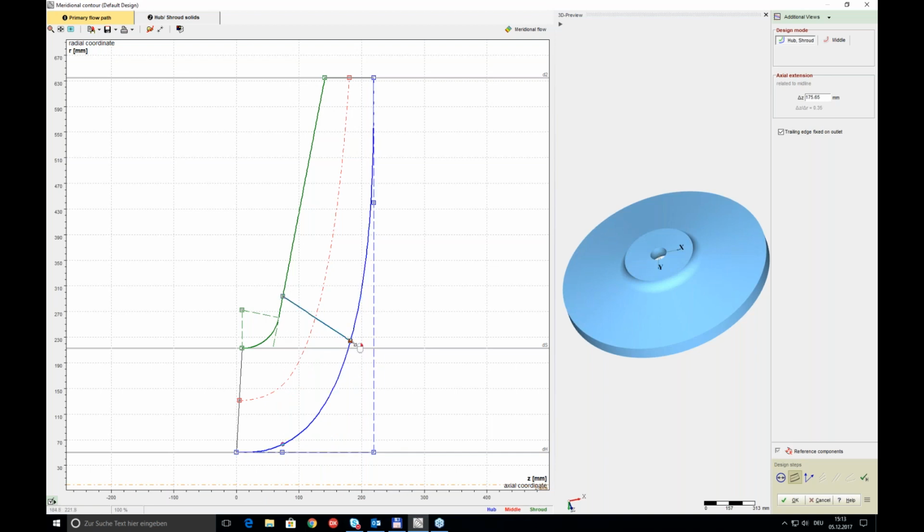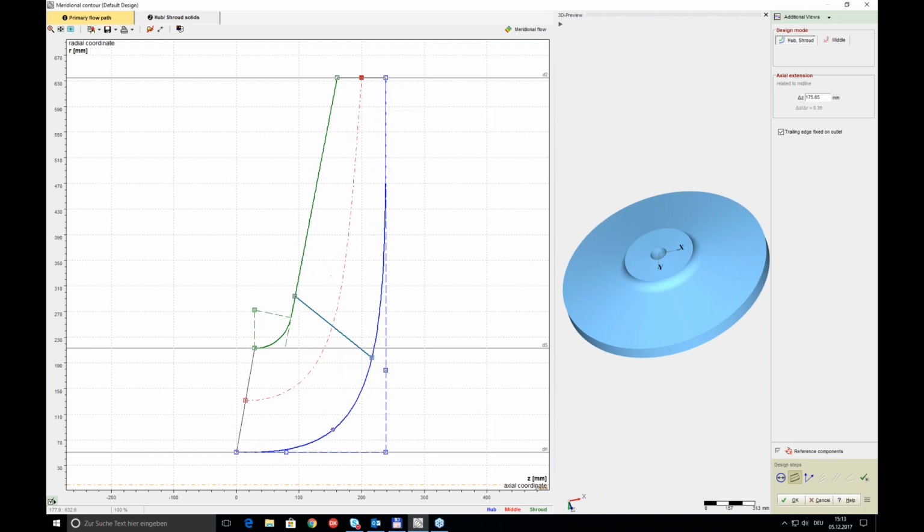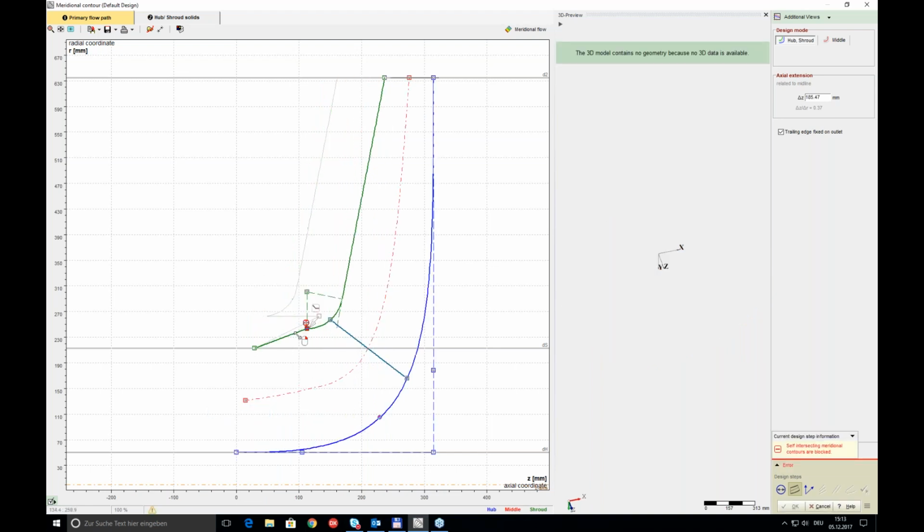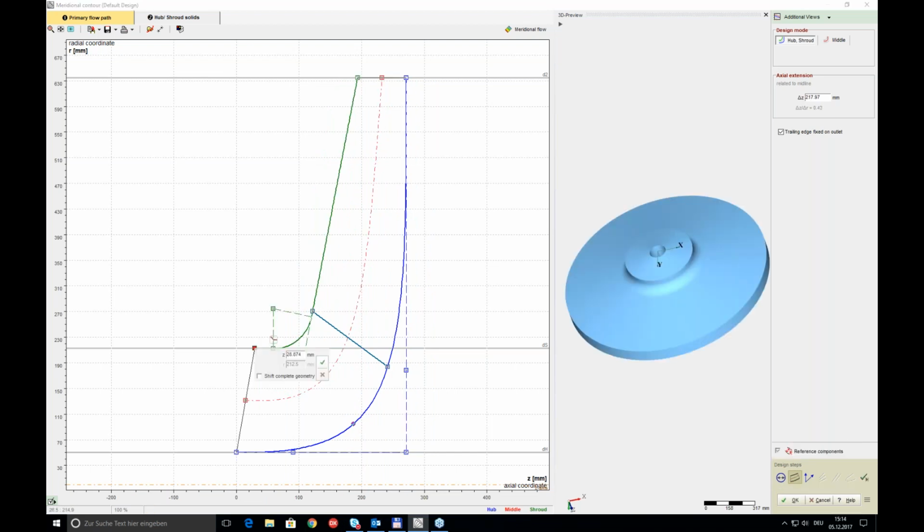And very often for centrifugal fans, impeller as well as the volute are made of sheets of metal, and that's why I leave the shroud contour to a linear part and a circular arc part. So the only one I'm going to change here is the actual extent, which can be 200, for instance. And I want to have here another linear piece at the suction mouth, and that's why I'm going to add another inlet curve, put it on my DS diameter, and also put this value to 0, and maybe adjust this circular arc diameter a bit.